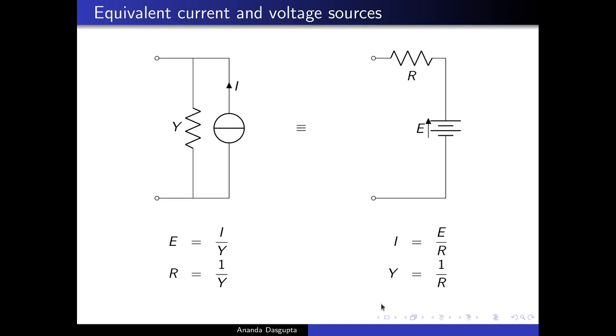And you can know this through the equivalent connections here, that these two demands are contrary to each other. A near ideal voltage source with a very small r would be equivalent to a current source but a very poor current source. A near ideal current source would be equivalent to a very poor voltage source. So, near ideal current sources can be manufactured in the lab, and there are actually near ideal current sources, which we often call just ideal current sources, in our laboratory as well. But near ideal current sources are much more difficult to manufacture, they are costlier, and they are not so common in daily life.